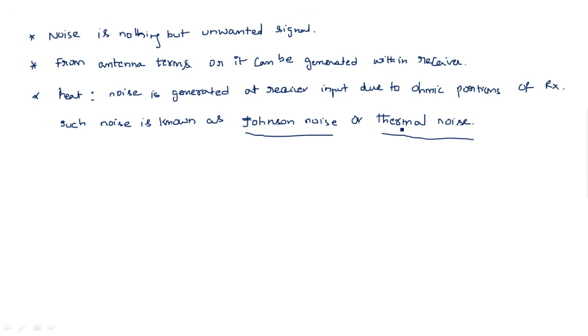Okay, how can you express this thermal noise? How can you write the equation for this thermal noise? Thermal noise is proportional to, what are the factors it depends on? Temperature, the temperature of operation at that particular time, and the bandwidth of the receiver. So what is the bandwidth of the receiver in the entire set of receiver blocks?